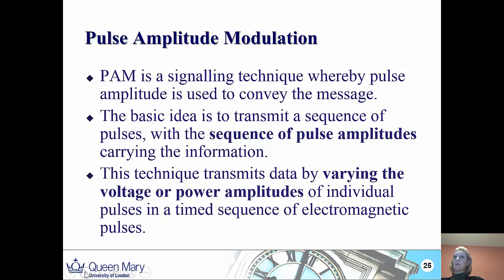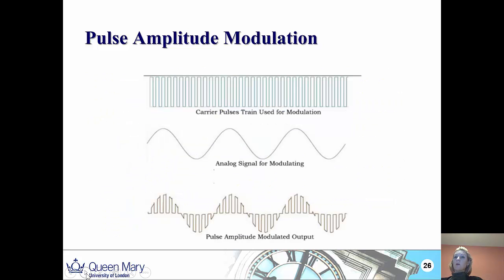The purpose of this carrier is to transmit the information through space as a wave, as an electromagnetic wave, or it's to allow several carriers at different frequencies to share a common physical transmission medium by frequency division multiplexing. So by using different frequencies, we can communicate multiple streams of information simultaneously. So it's how we want to use that communication channel in order to convey this information.